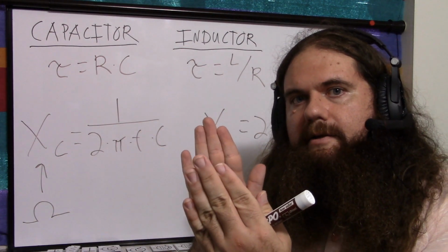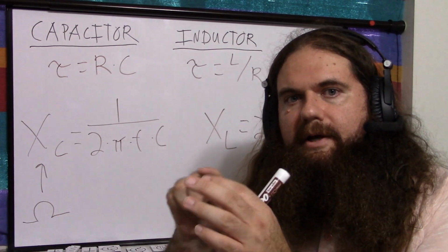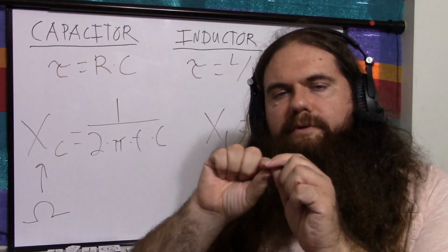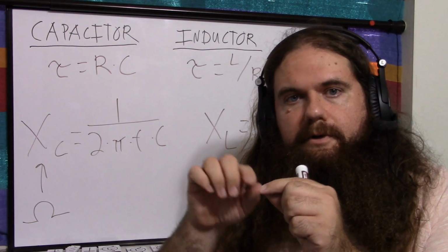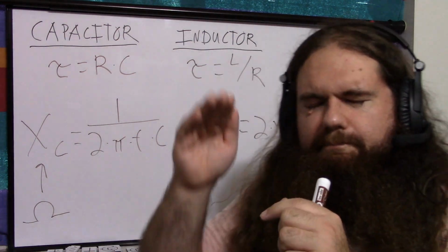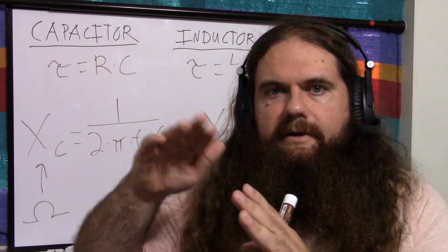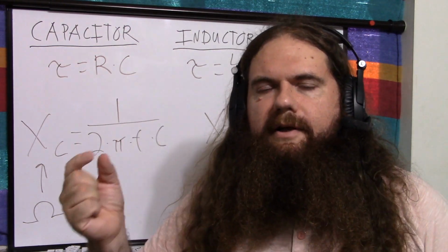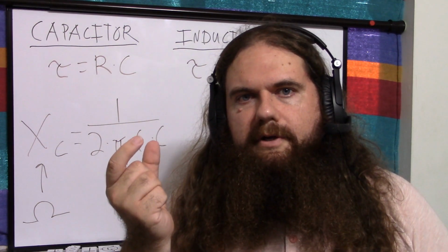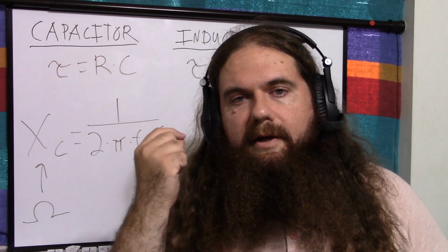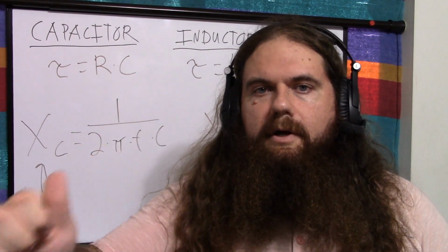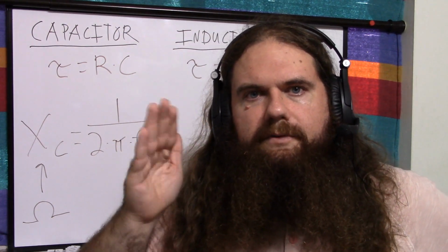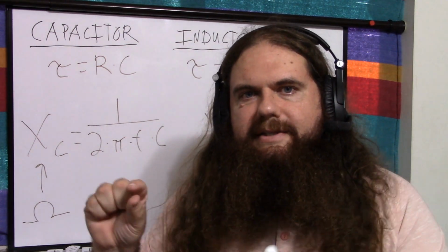It's going to delay the signal, phase shift it, but your signal is not really going to change much because it's got plenty of time to resist the increased flow of current, or counteract the decreased flow of current. Magnetic field strength changes and it stabilizes again. The faster the frequency, the less time you're giving it. So if you have a really high frequency signal, then it's going to spend the vast majority of its time giving you strong back EMFs to oppose an increase or putting out strong current when the field is collapsing, and it's charging and collapsing really, really fast, and it never gives it time to really let the signal through.